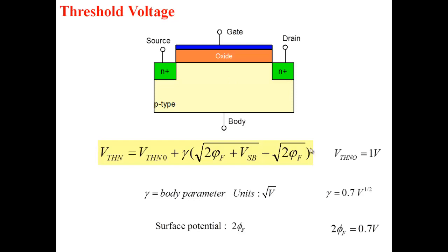You also have the freedom. Every technology will say you can use a channel length above a certain limit. A technology defines a minimum channel length. We have been saying 180 nanometer. So the technology is saying minimum channel length is 180. You can use anything larger than that. So as a designer, you can have a MOSFET which is maybe 360 nanometer channel length, double the channel length, or 3 times, or whatever. It's up to you. So the technology allows you that freedom.